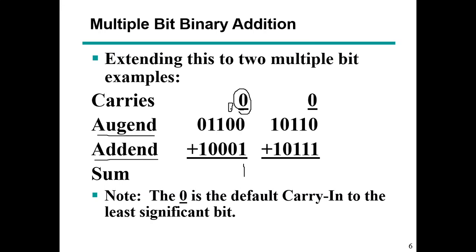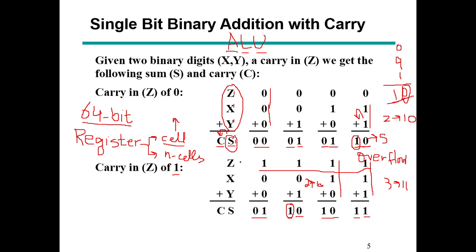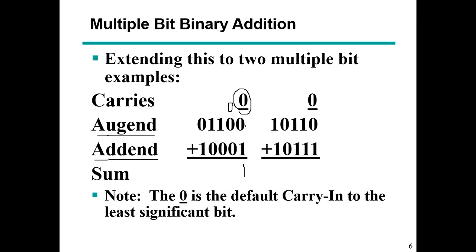So now I guess you would realize, why did we always consider here the carry in? Why? Because whenever you add 2 bits, here the carry in is assumed to be 0. So there may be a carry out. For example, if it were 1 1, there would be a carry out 1. That would be significant. Right now the carry out is 0. It is not that significant, but in any case you should always consider a previous carry. So in this case there is no previous carry.